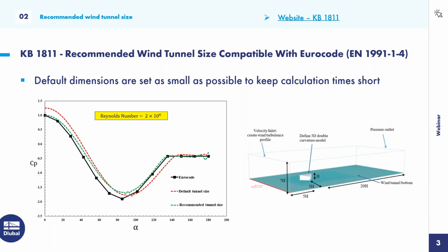And this is, of course, a model of surfaces and vortexes. So it's a 2D mesh, which will then be hidden within a computational mesh. So it's a simplified triangle mesh, which is given over your structure. And this will then interact with a 3D solid mesh, due to the fact that we, of course, have to calculate in our CFD with solids. So putting a wind pressure into the inlet, which then has, of course, to go through the whole tunnel and on to the outlet.